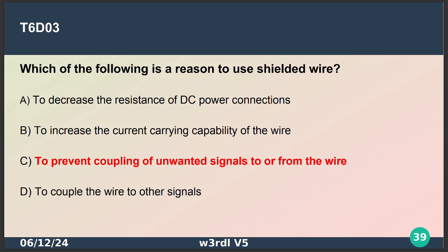And then I wondered why, while I'm sitting there looking at it and nothing's moving, my line was all over the place. It was because it was coupling to that 40-meter antenna. Once I took the 40-meter antenna down and got it out of the way, it was just as flat as could be.